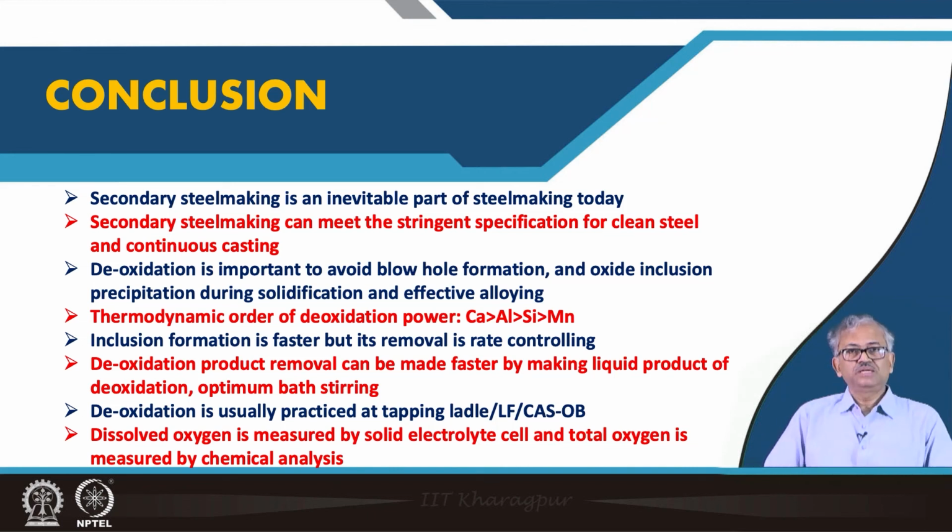And we have said that deoxidation is practiced during tapping also. Here you can utilize the inertia of the tapping stream, such that you take an aluminum bar at the bottom of the ladle and then pour the liquid steel over it, and then the aluminum will melt and dissolve and deoxidize. So you can use the inertia. Another thing is that if you keep aluminum at the bottom, the liquid steel also will not directly hit the refractory wall. That is very important.